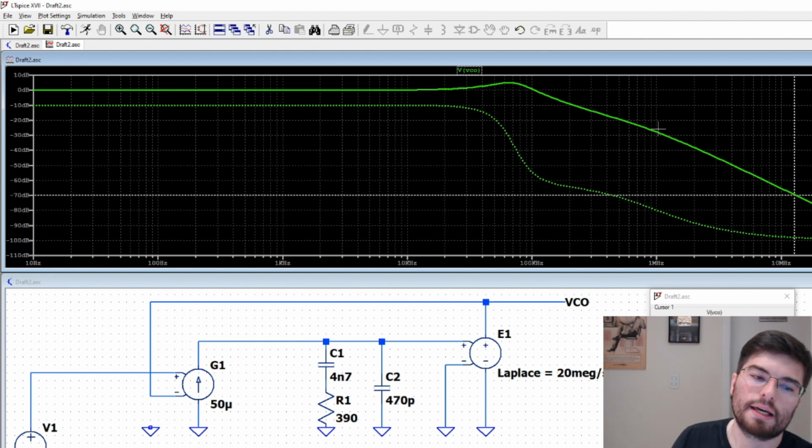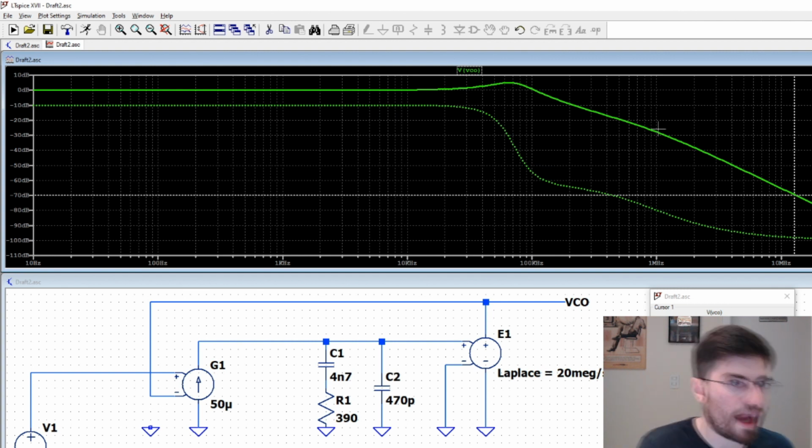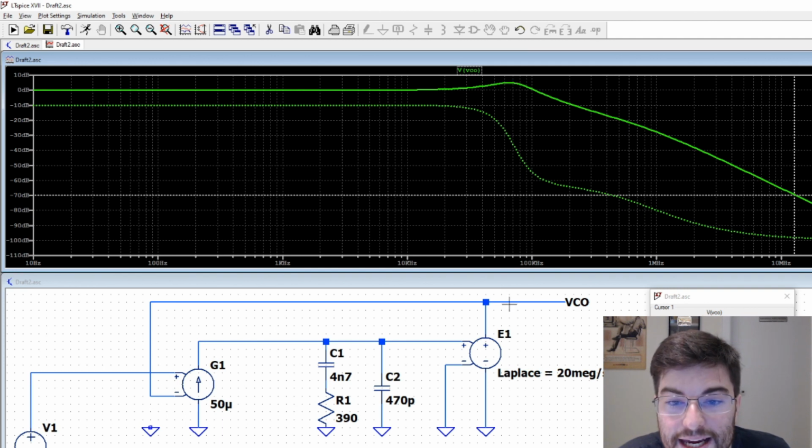In this situation, I have a pretty clean phase noise reference because I have a crystal reference. So I'm trying to have a broadband bandwidth in the PLL to control the VCO over a broadband bandwidth to have a cleaner VCO.